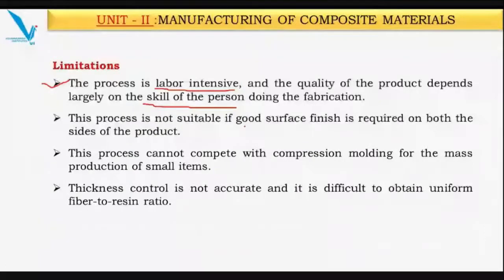Good surface finish on both sides. What we have seen is that you will get a good finish only on the mold side, but on the opposite side you will have a rough finish. If you want a good, glossy finish on both sides, then this process may not be suitable. So this process cannot compete with compression molding for mass production, where automation is generally done.